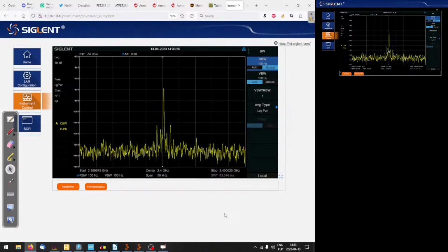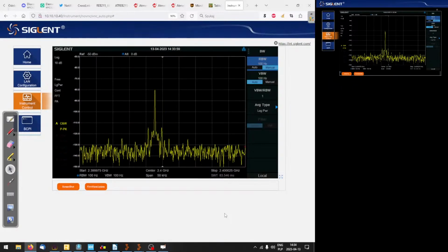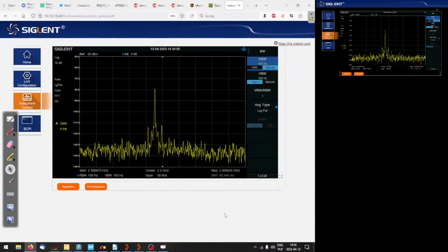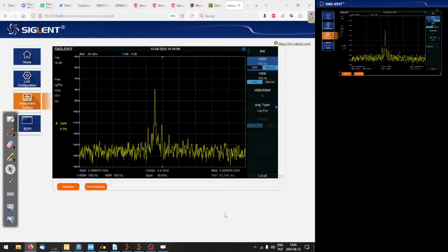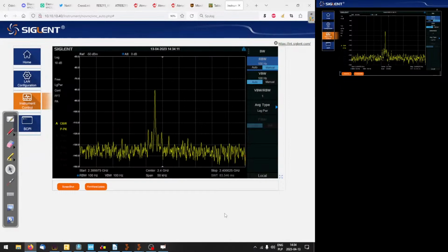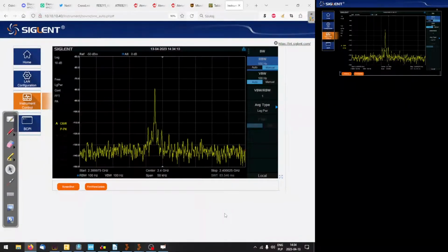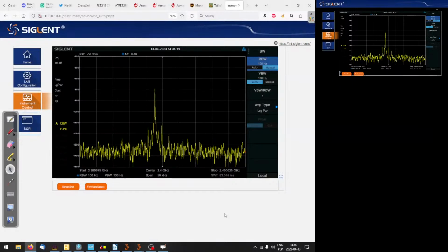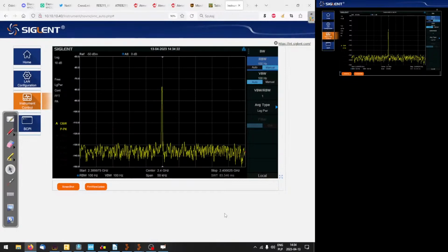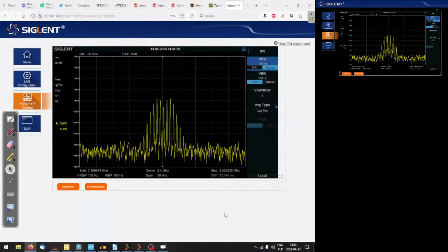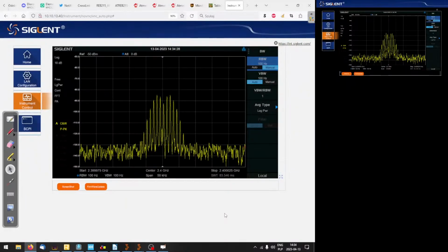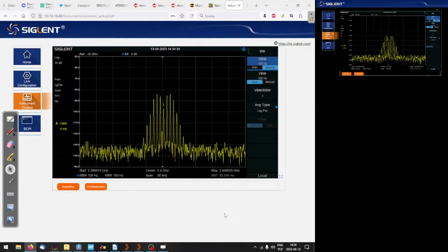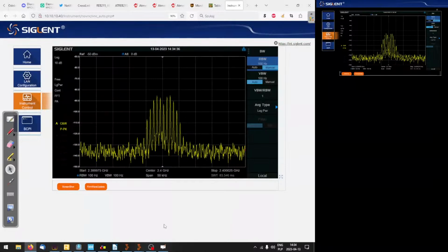And now I'm going to apply a 1 kilohertz sine wave. So we need to do this. I'm looking at my signal generator. And in just a second, you should be able to see a nice modulated carrier. All right, so the frequency is set. That's our signal. Of course, that's expected. That's a 1 kilohertz modulated carrier with nothing else, just the sine wave of 1K.